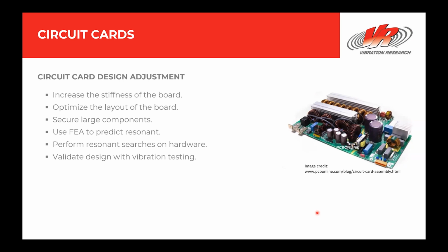Without an understanding of the operational environment and modes of these systems, it is not unusual for large circuit board assemblies to have natural frequencies that cause large components, such as capacitors or inductors, to fatigue and fall off. For these systems, it is especially important to use analytical methods to predict modes and then to verify in the lab and adjust designs to ensure that resonant frequencies are at least a factor of 2 above the harsh vibration environment that these systems must survive in.